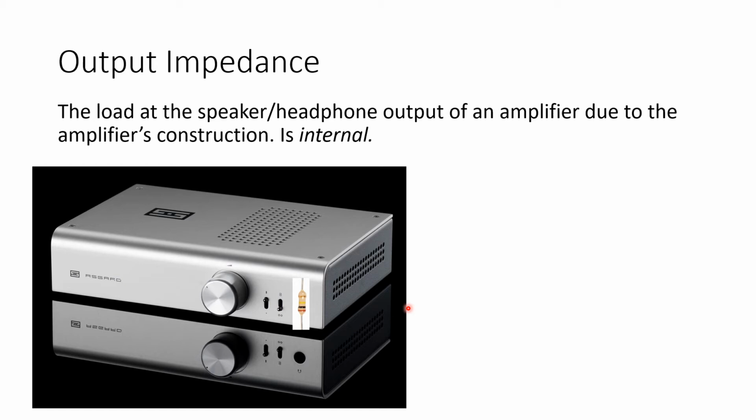And so if you were to just plug your headphones directly into a speaker amp, you'd probably blow your head up. Just way too much power going through there. So they put a resistor in front of the headphone output to drive up the output impedance and thus reduce the amount of energy that was going to the headphone. And so that increased the output impedance, and that's where, at least with headphones, we started to need to worry about this thing called impedance matching, where you're worried about output impedance and the impedance of your headphones and that sort of thing.